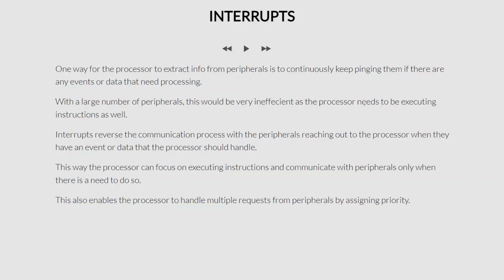So in the previous lecture I gave an overview of timers, of the three timers which are present in the F28069 and how these timers work, the fact that you can load a period value into their registers and you can also load an optional prescale value so that you can actually increase the time period that you can configure. And at the same time we also saw the control register, the fact that you can start and stop as you want, and you can also enable interrupts.